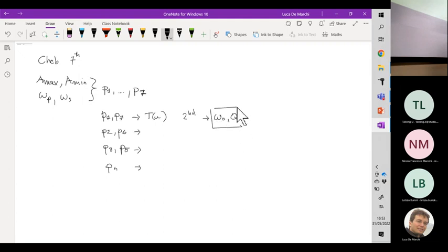And this is all you need, okay? So omega null and Q for the first complex conjugate pair, for the second, for the third one, and finally for the fourth. Well, actually, the fourth is a single pole, so you just have the information related to omega null, okay? The pole position, the angular frequency.